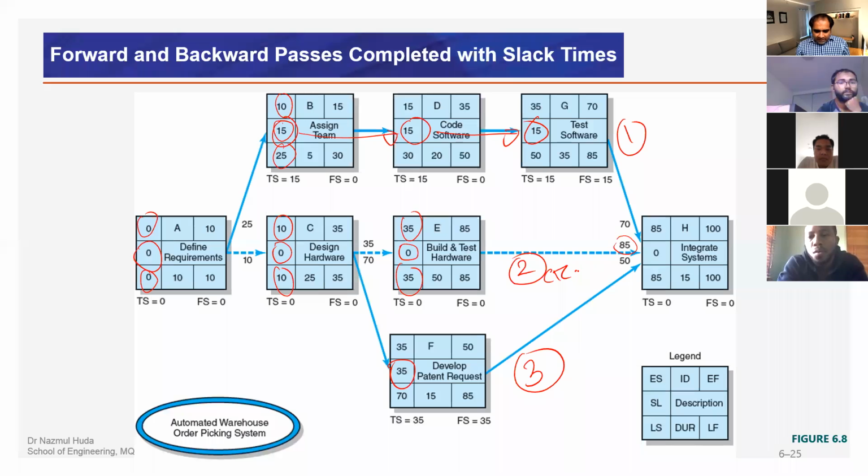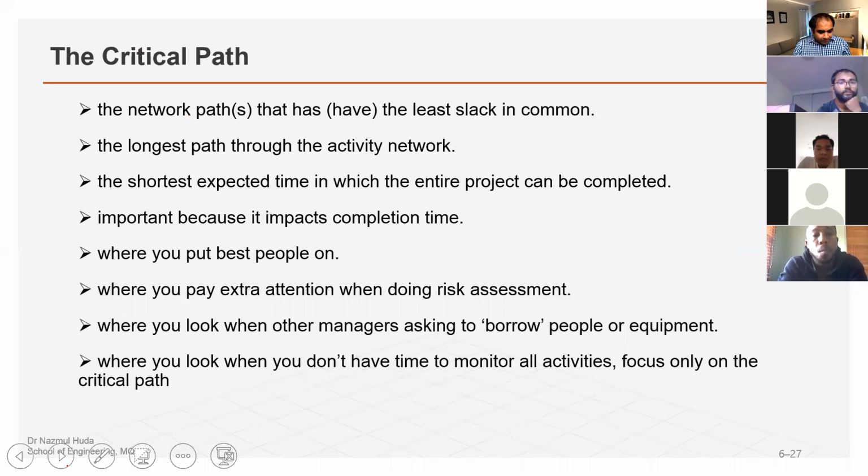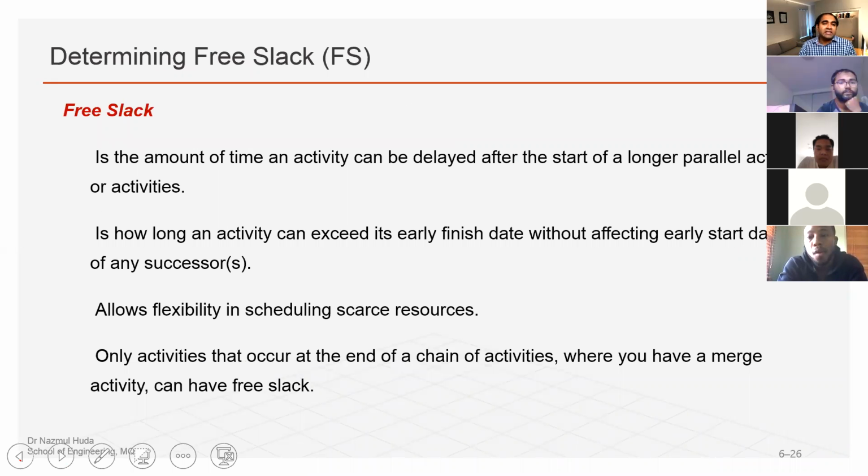Okay, then the next is, what is free slack? This is a bit different from the total slack. Free slack is related to each activity. It is the amount of time an activity can be delayed after the start of a longer parallel activity or activities.